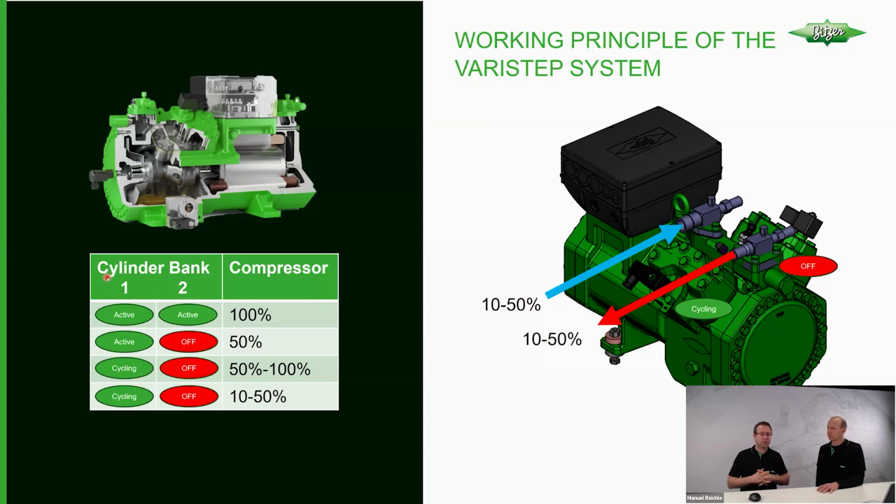If we don't do this, we will end up with a broken compressor, or a compressor that at some point will show a discharge gas temperature far away from 284, 300, 350, easily possible. So we increase the speed or the capacity of the compressor, and then the rack controller identifies that I have too much capacity in the system.